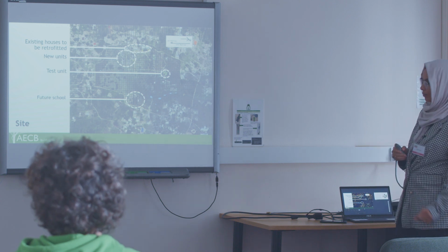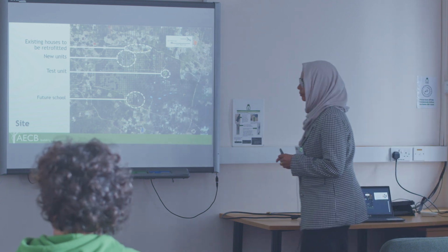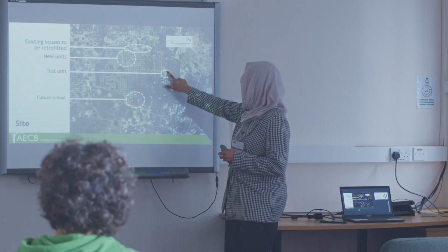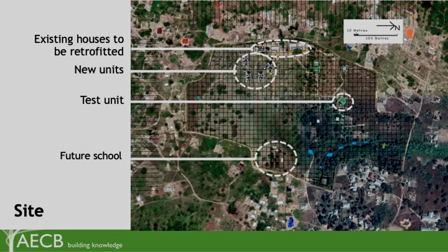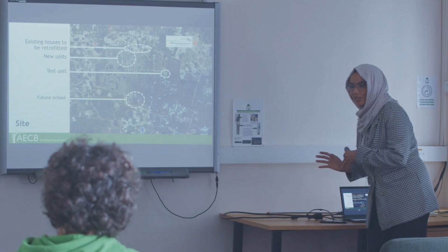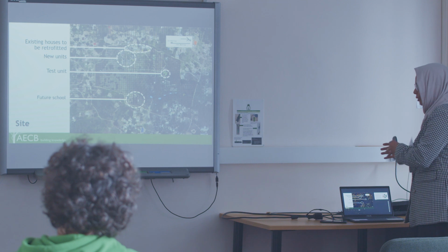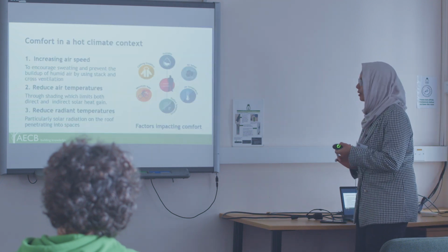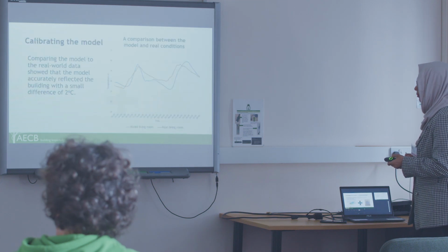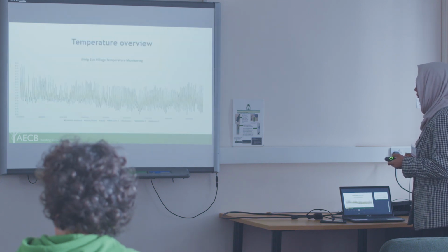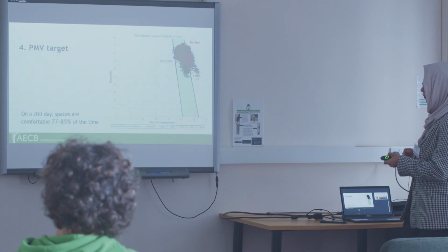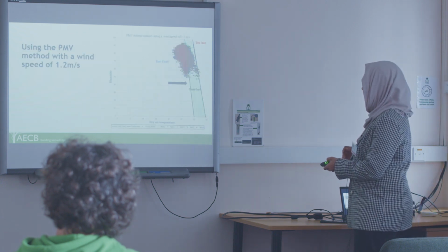So I imagine that by planting fast-growing trees around the building, we're going to get a significant cooling effect. But it will take time for them to mature. This is the test unit, and it's very woody over here, but this is a bit more open, so there's windfall. We have to be strategic with those trees. They provide shade, yes, but they might block the wind flow. So you have to design them in a way that achieves both. And what we're hoping is that these will become rules of thumb, so that we can apply simplified design codes that might allow this type of approach to be applied to somebody's house, locally.